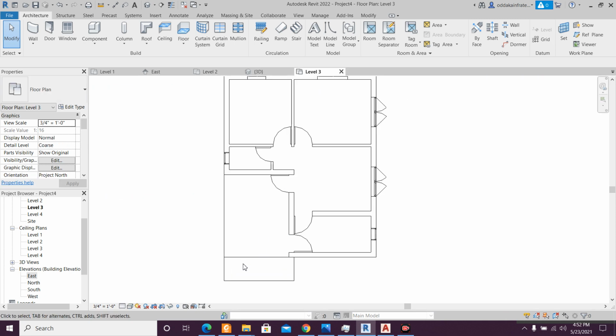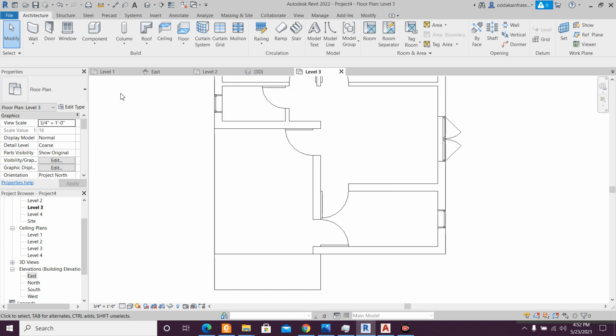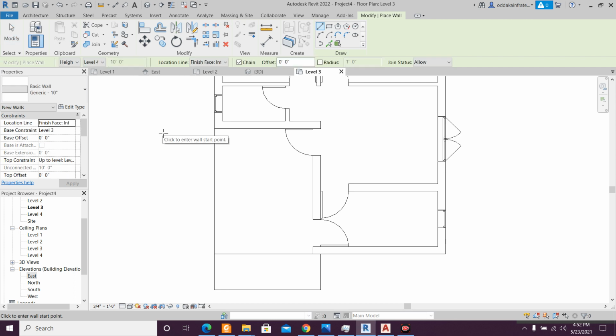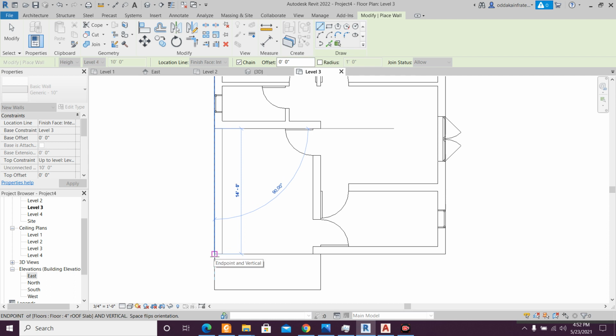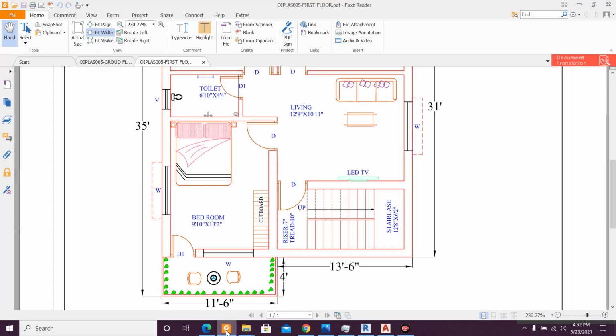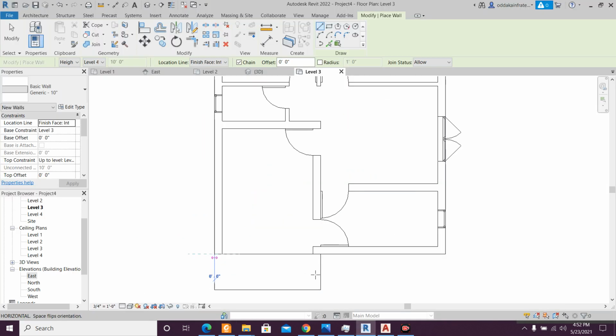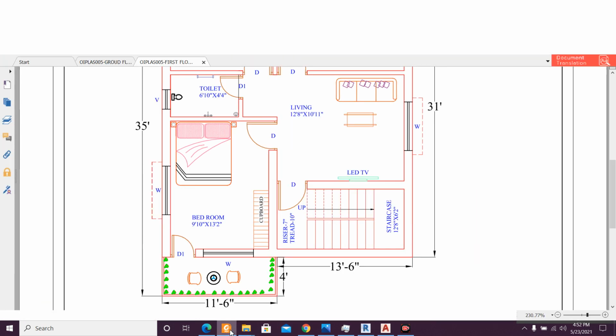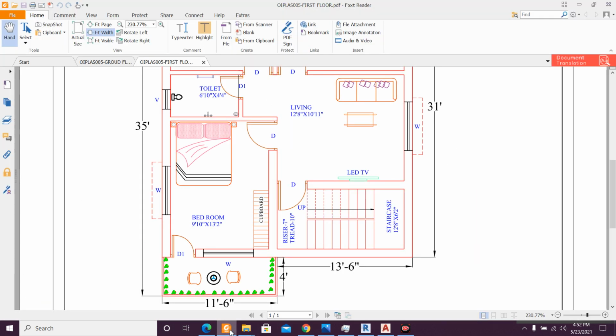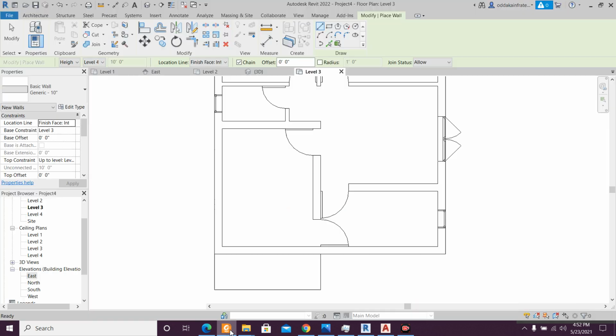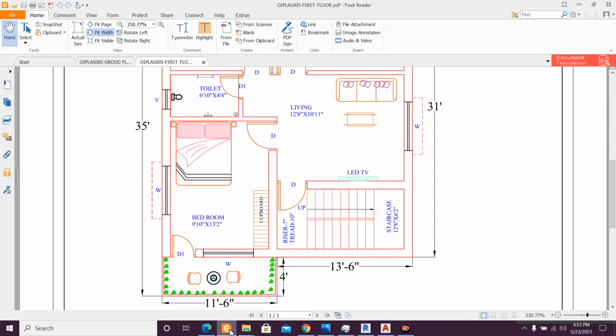Go to level 3, and I need to go to WA, enter. So not WA enter, only WA. Just have this basic wall here up to this much. I click, and here also I think we need the wall. Yeah, here also we'll make the door later. Here also we need the wall here, and once the wall is done, we can have railings here actually.